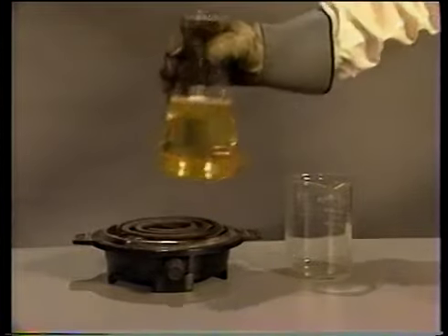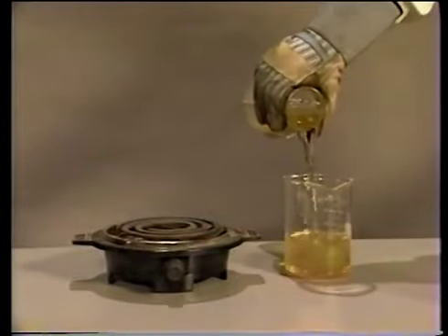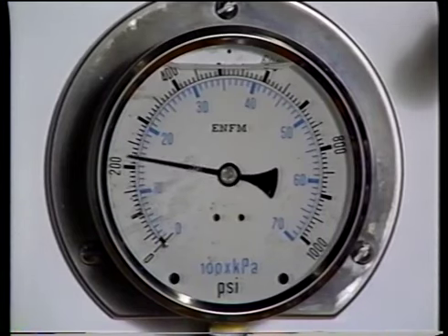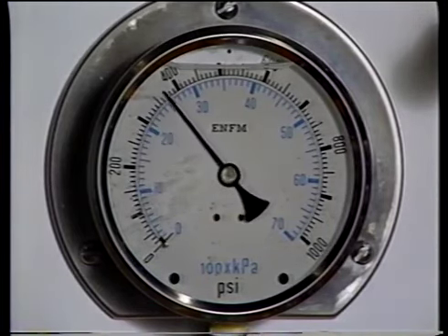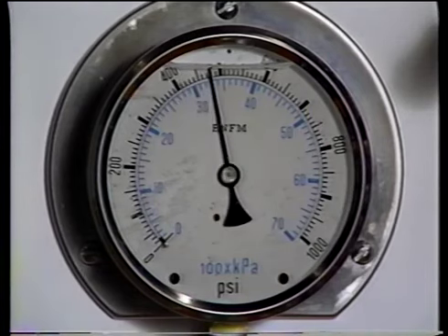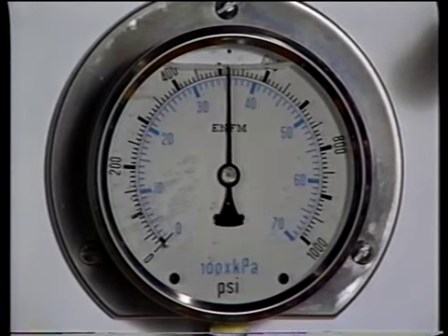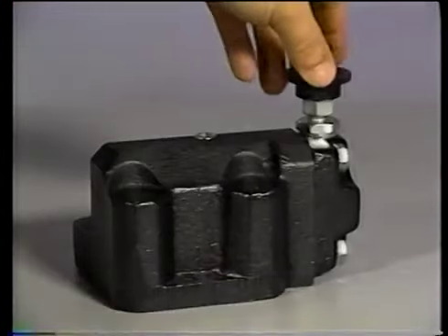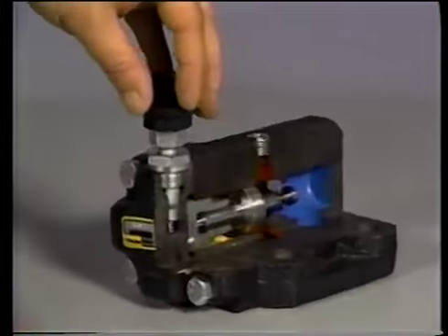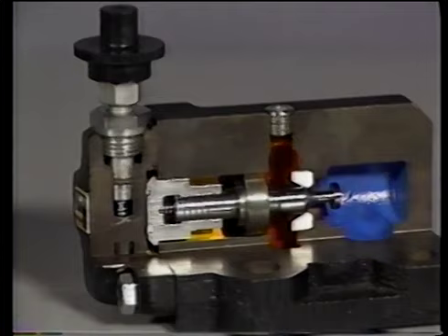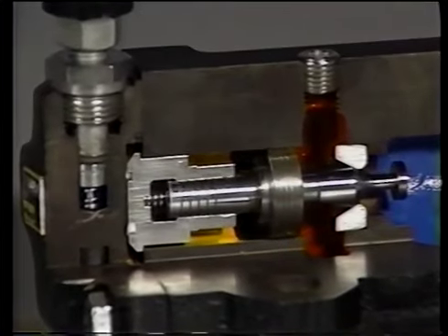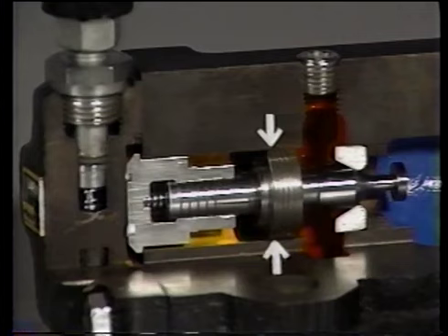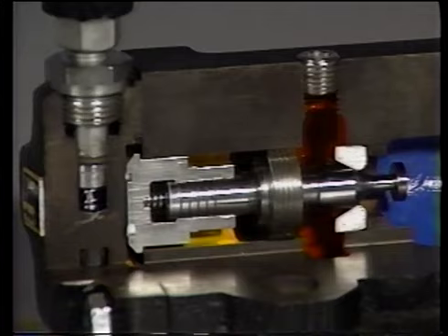If we raise the temperature of oil, its viscosity decreases and it flows more easily. Pressure has the opposite effect on viscosity. As the pressure goes up, the viscosity of a liquid increases. Making sure a hydraulic system has fluids of the correct viscosity is important for two reasons. Components like this valve are built with very close tolerances between parts. Fluid with too high a viscosity could not get into the small clearances between moving parts to provide the proper lubrication. The lack of lubrication will cause excess wear and could lead to complete failure of the component.